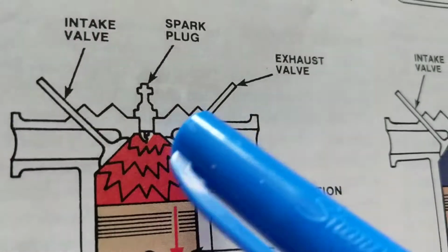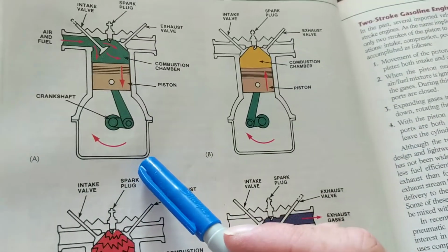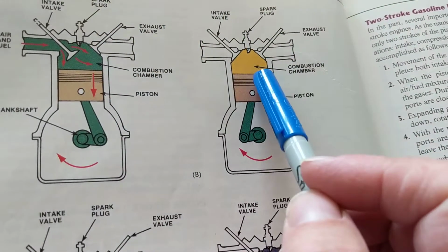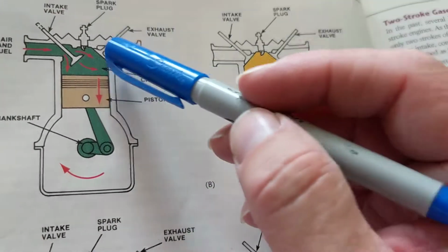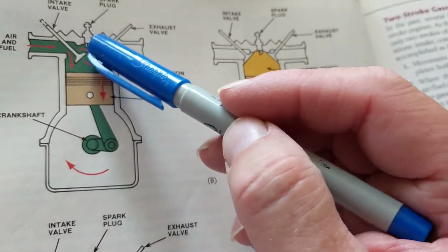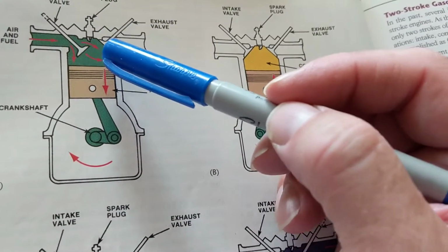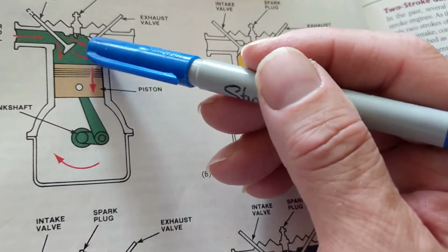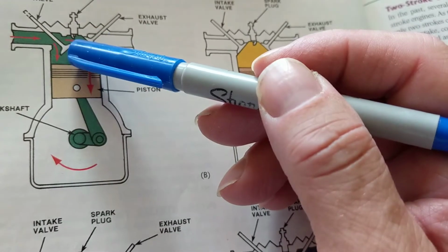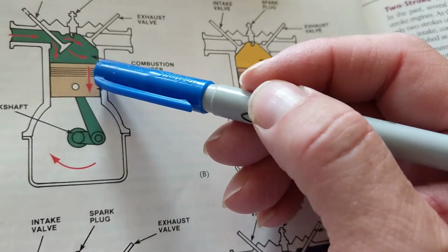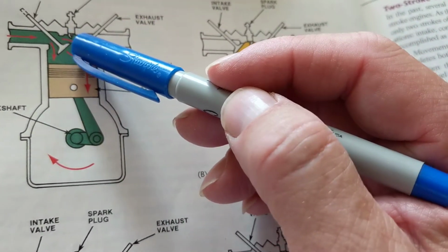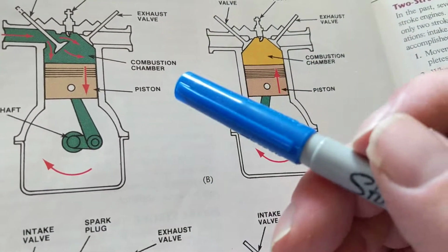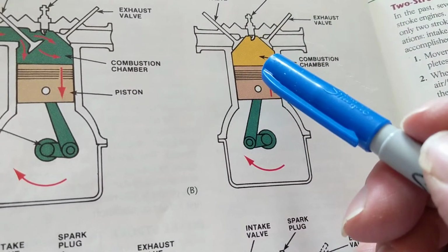So when this is closed, look again, compare. First, the air fuel has to come in. Then we have to squeeze them together, as we try to get as much air fuel into this area as we can. That's why this piston is going down. When this goes down, the volume of the space increases. You can put in more air and more fuel. This is going down from here to here to here. More area means more air, more fuel. That's great. That means more compression and a better spark, more ignition, more combustion.